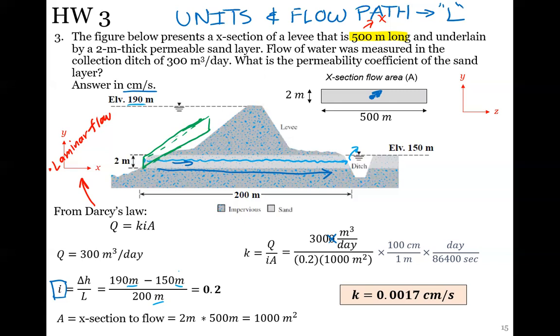So I'm not going to give you this. You need to know Q equals KIA. Has everyone seen that in your hydraulics class or anything? I know some of you haven't taken fluid mechanics yet, and this is the part of geotech that needs that. But really, it's only that equation. So Q equals KIA. It's easy to say. Q equals Kia. I don't know, they had hamsters driving a car, so you could remember it that way. The hamsters were cute. But Q equals KIA, and it works that way.